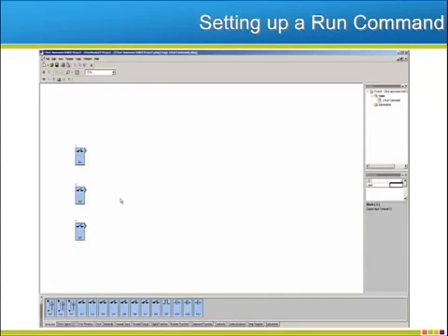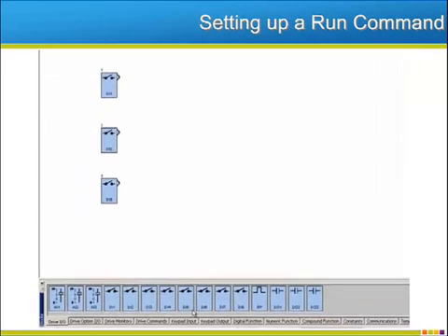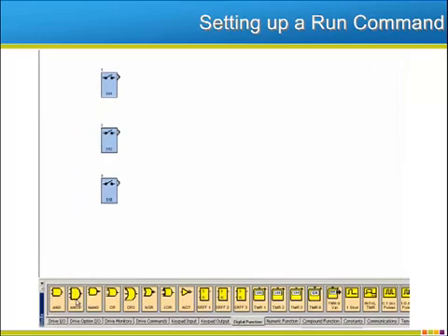I need them all to be closed to make the drive run forward, although I do not care about the order in which they close. I will use the AND3 block. This block accepts three logic signals in and outputs a logic signal of true when all three inputs are true.